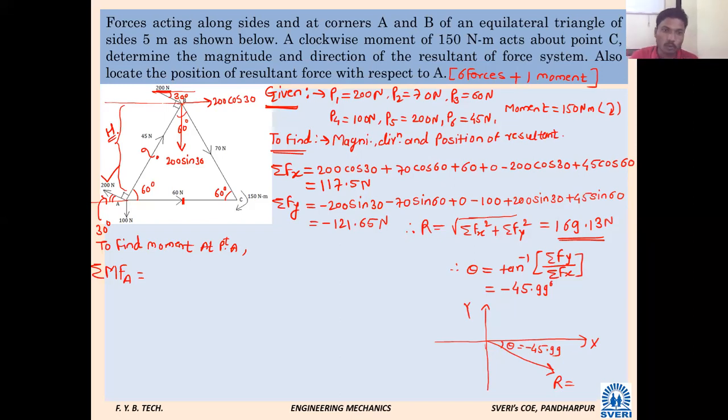Let us go now with this. First, the force we will consider is 200, and again its component. So 200 cos 30. That force is horizontal, acting at point B. Point A is fixed. How will the object rotate, clockwise or anti-clockwise? Clockwise. Very good. It will rotate clockwise. So 200 cos 30 into the perpendicular distance.